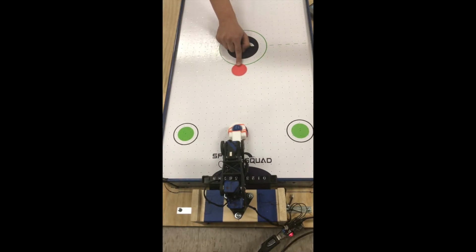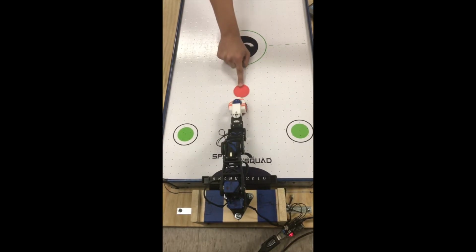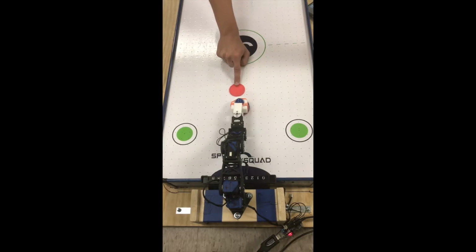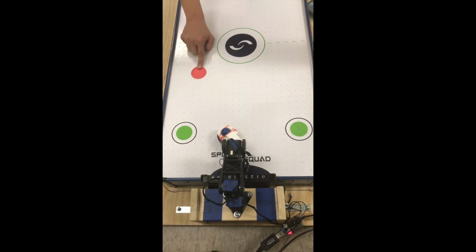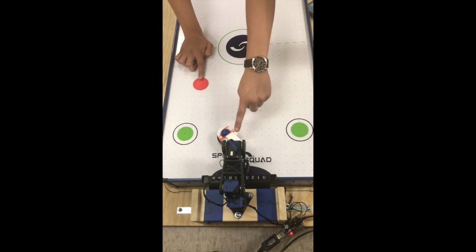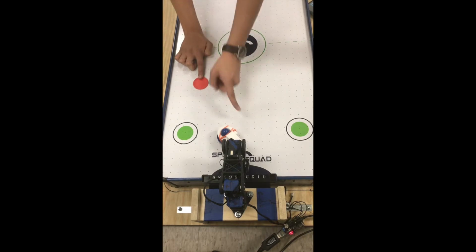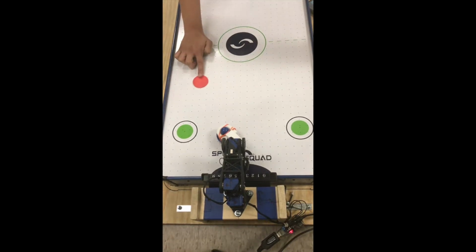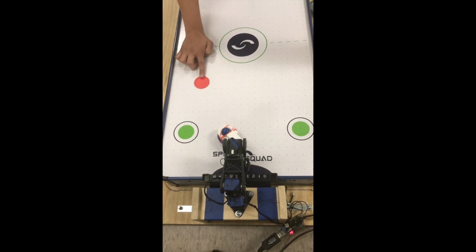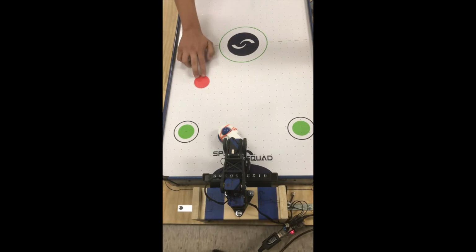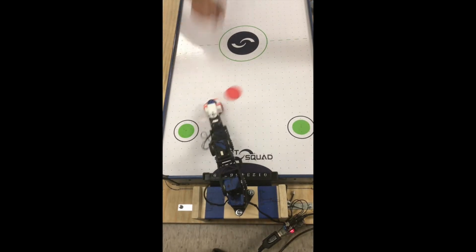If the puck is within plus or minus 5 degrees of the vertical axis, the striker prepares to hit the puck head on. If the puck is outside of the range, the Rex arm still tracks the puck, but rotates the striker 45 degrees away from the tracking line. Once the puck approaches, the striker moves towards the puck and rotates into the line of the puck's motion to hit the puck as hard as possible towards the opposite goal.